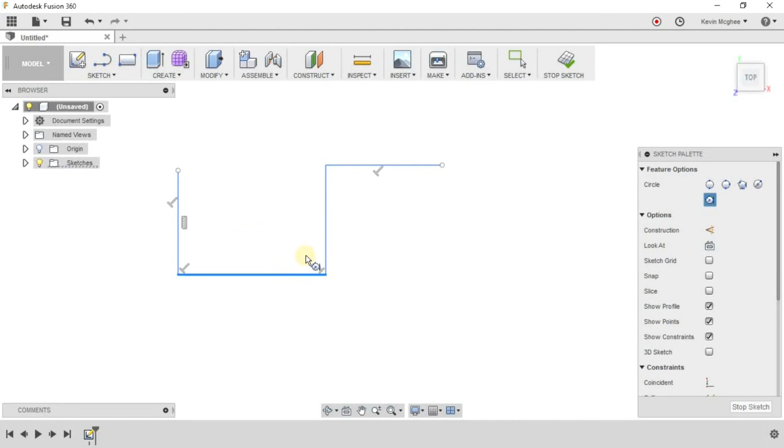Select first tangent. Select our second one, and we can draw a circle in such a way that the edges, think about it, in this case the 3 o'clock and 6 o'clock are attached perfectly tangent to the line. What that means is the best way I describe it is if you were in a car and you were going around this round racetrack and going round and round and round, you wouldn't need to turn at all to get onto this line and drive out of the circle. It's nice and smooth, it's not rough or difficult. So that's two tangent, using two lines.